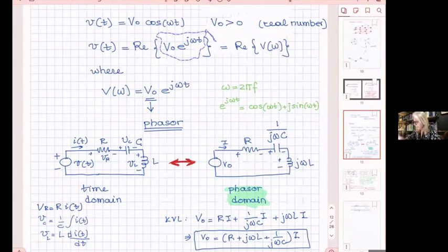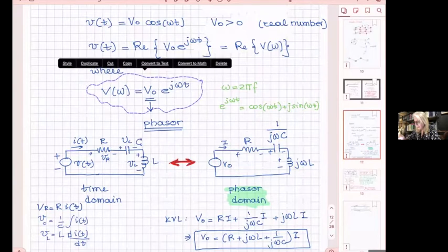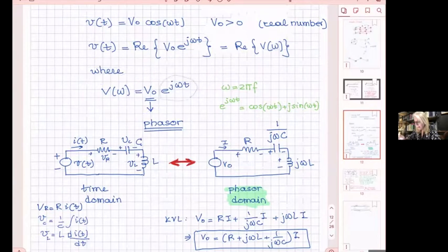This complex number is a function of frequency and time, but in a different way. And then from this complex number, we assume that always this is going to have the j omega t dependence for any harmonic or monochromatic excitation, and we keep only the amplitude here, and we call this the phasor.